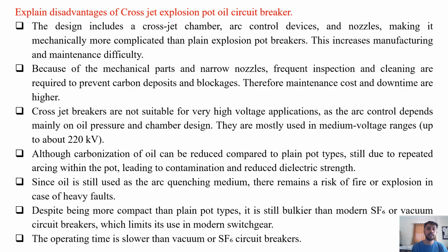Explain disadvantages of cross-jet explosion pot oil circuit breaker. So the design includes a cross-jet chamber, arc control devices, and nozzles, making it mechanically more complicated than plain explosion pot oil circuit breakers. This increases the manufacturing and maintenance difficulties.